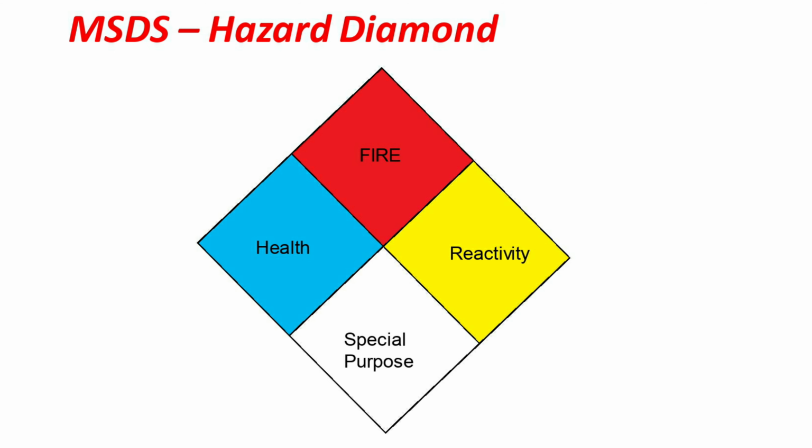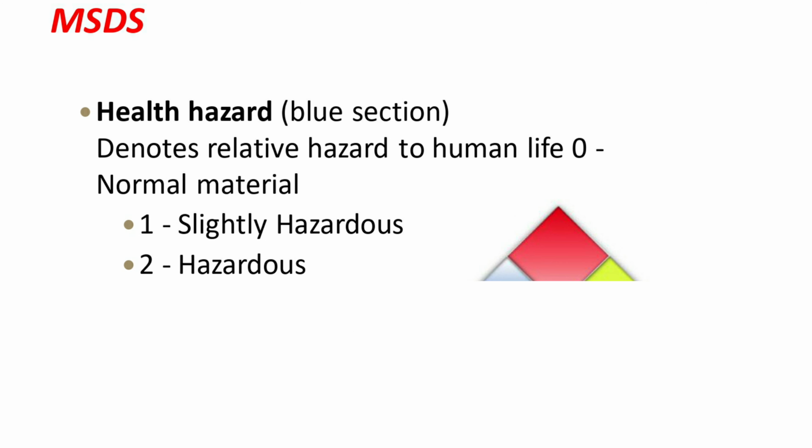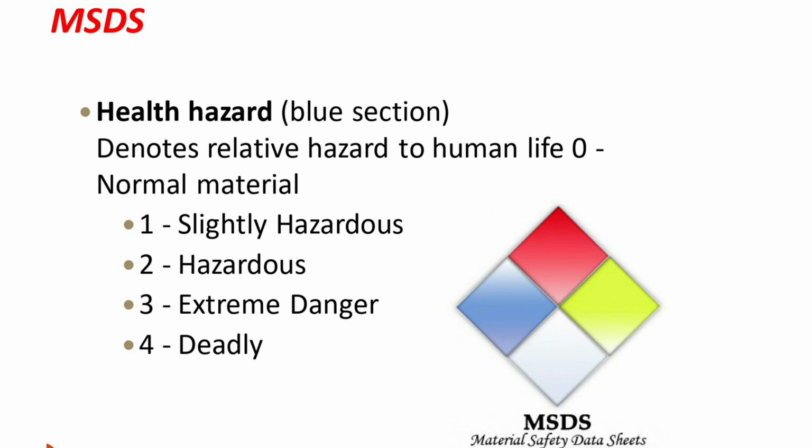MSDS, hazard diamond. 1. Fire. 2. Health. 3. Reactivity. 4. Special purpose. Health hazard, blue section, denotes relative hazard to human life. 0. Normal material. 1. Slightly hazardous. 2. Hazardous. 3. Extreme danger. 4. Deadly.